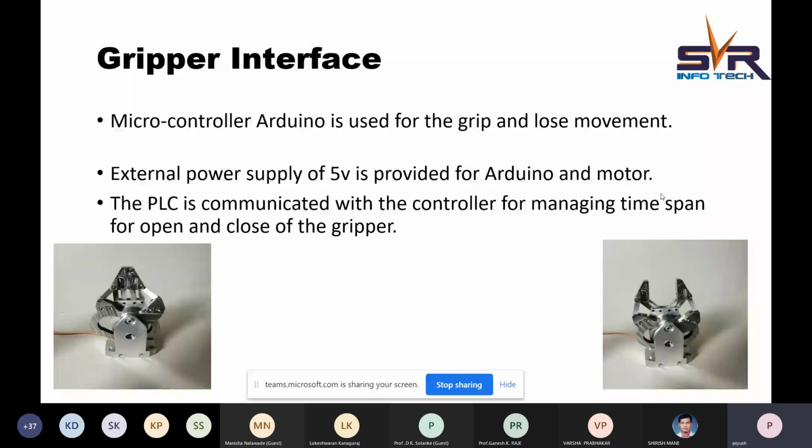If you switch to some other pin, that becomes a little bit complicated and isn't giving good results, because the power supply needed for the servo is also quite high, and that is not available in the case of PLC. So this is another reason that we have to use an extra module and make it available here.